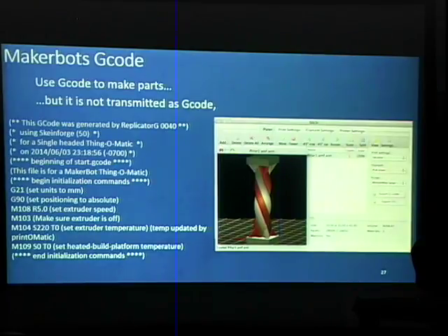I don't use the MakerBot software. I use a thing called Slicer that is CAM software to, rather than computing machining code to remove material, subtractive manufacturing, compute a shape via additive manufacturing. It slices it into individual layers that it then prints. The really nice thing about Slicer and the G-code generated from MakerBots is it's incredibly verbose with commenting. So if you wanted to learn about this, go make one of their files and you can just read through and it tells you exactly what it's doing.